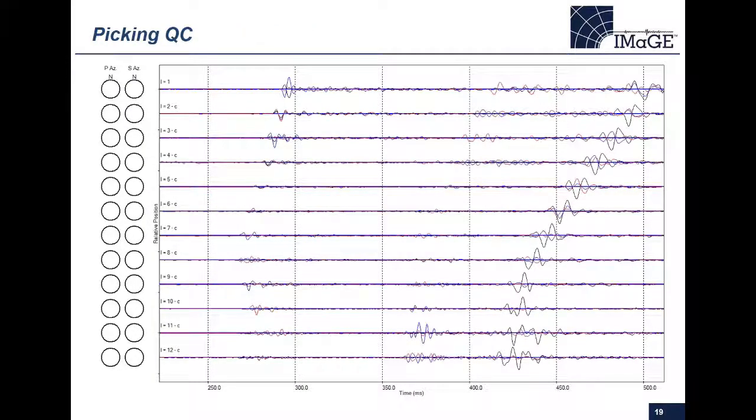All right, so to go along with velocity model calibration and orientation, you really need to make sure that your events are correctly picked, and that however you pick your events for your calibration is the same way that you're going to pick your events for any processing that you do. So this is just an example of a waveform. It's a pretty nice and clear waveform. You can see a few different phases, like the P here. We've got one shear phase here and a secondary shear back here. So we'll just put on a P and, in this case, an SH wave.